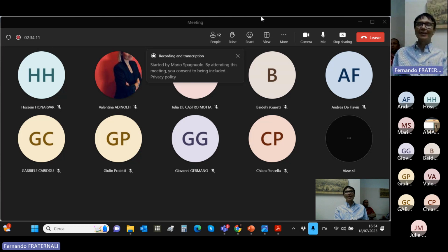So if you are in a case in which there are warping effects, the fact that the cross section does not remain rigid, so there's some warping out of the plane of the cross section, in most cases, with these corrective factors, in the end you account for these effects, for example, in terms of energy.